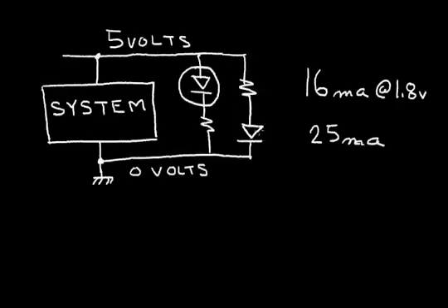And since the LED is going to be on the front panel, I think I'd prefer to put a little lower voltage at the front panel. So I think I'm going to erase this, and choose the configuration with the diode connected to the ground.